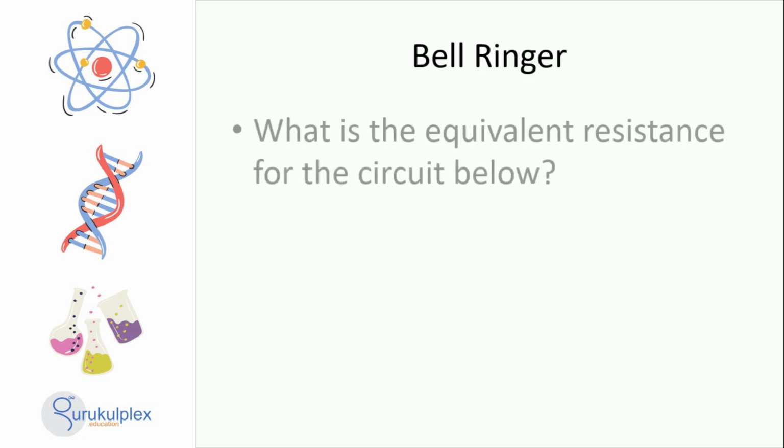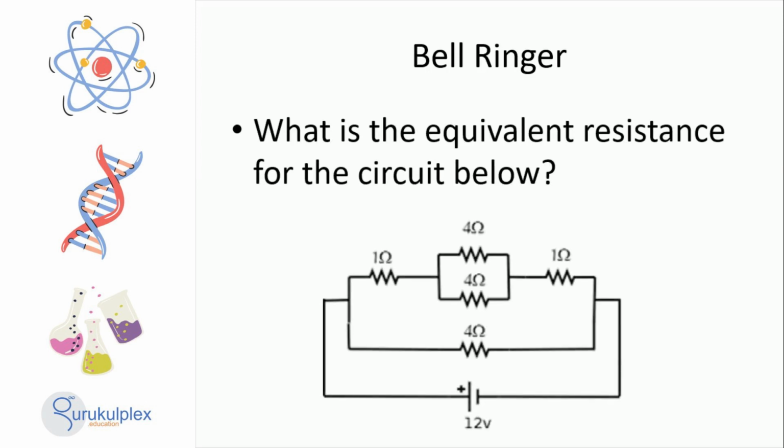Using Ohm's law and Kirchhoff's law for resistors, the equivalent resistance of the circuit can be calculated. With 3 resistors in parallel, the total resistance of all parallel connected resistors is equal to the reciprocal of the sum of the reciprocals of all the branches. Therefore, the equivalent resistance of the circuit is equal to the reciprocal of the sum of the reciprocals of each of the resistors.